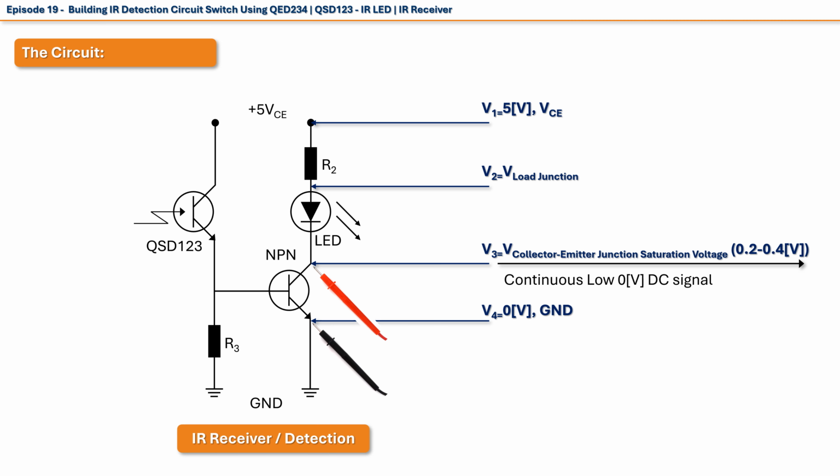From what point in the circuit can we draw the signal voltage? Let's mark all possible junction points with numbers from V1 to V4. Clearly, points V1 and V4 are directly connected to the positive and ground terminals of the power source. Their potentials are always 5 and 0 volts, respectively, and the state of the circuit has no impact on them. The only remaining two possible candidates are points V2 and V3.